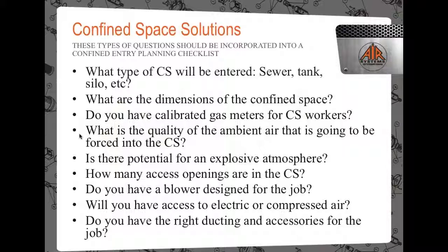Is there potential for an explosive atmosphere? How many access openings are in the confined space? Do you have a blower designed for the job? Will you have access to electrical service or compressed air? Do you have the right ducting and accessories for the job?